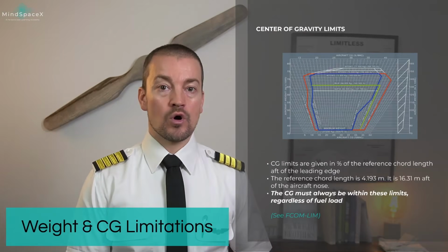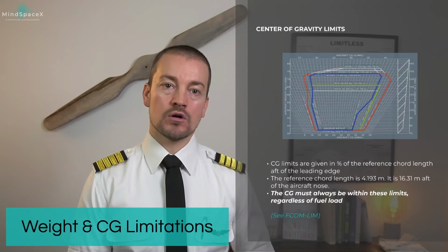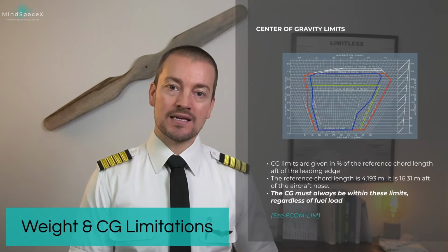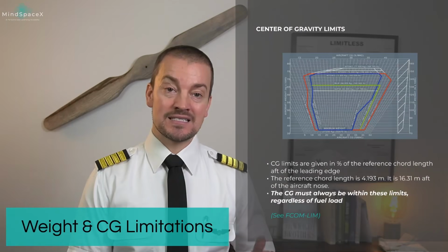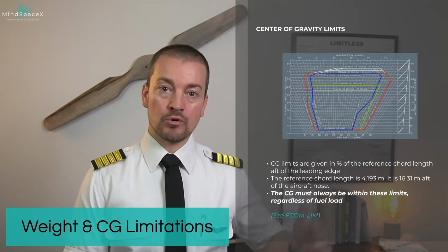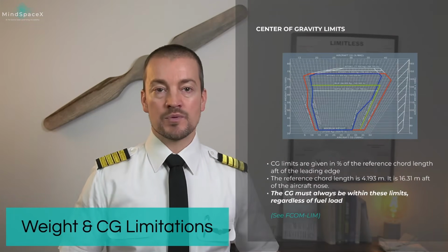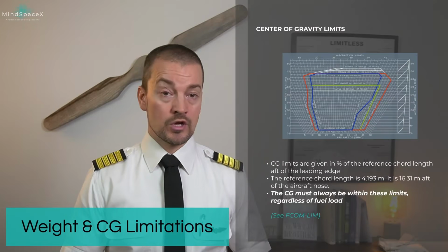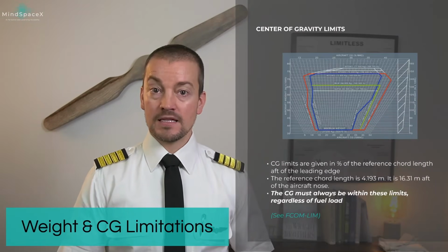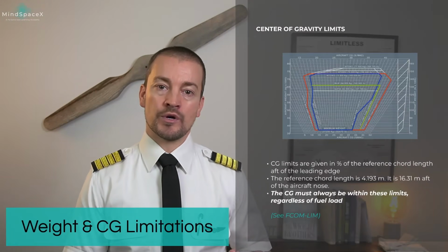The reference chord length is 4.193 meters long, and the leading edge MAC starts at 16.31 meters aft of the aircraft's nose. Both of those values are given to be able to calculate manually the position of center of gravity. We covered this in mass and balance in your ATPL theory. The CG must always be within these limits regardless of fuel loading on the aircraft.